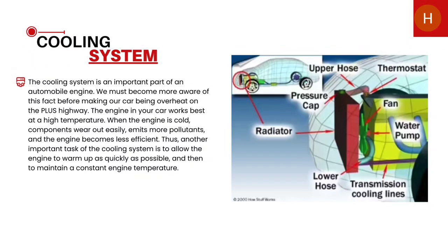The engine in your car works best at a high temperature. When the engine is cool, components wear out easily, it emits more pollutants, and the engine becomes less efficient. Thus, another important task of the cooling system is to allow the engine to warm up as quickly as possible and then remain at a constant engine temperature.